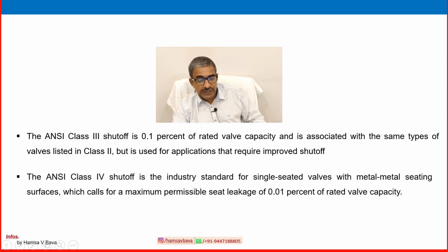Class 4 shutoff is the industry standard for single seated valves, that is important, with metal seating surface, where the maximum permissible leak is 0.01. Still it is reducing, rated valve capacity 0.01. You can note down these 6 classifications.